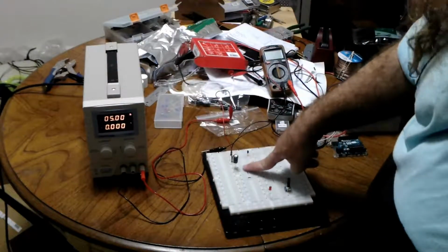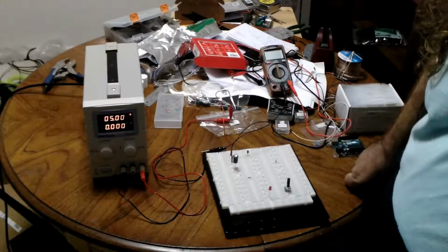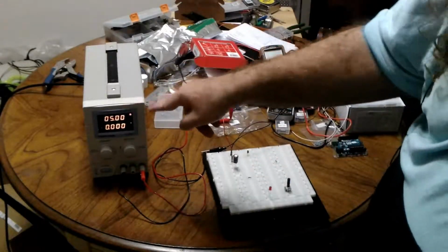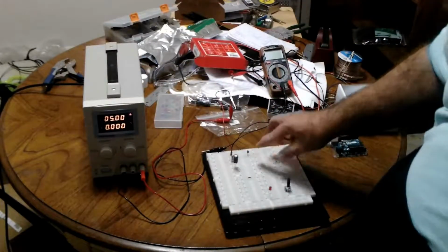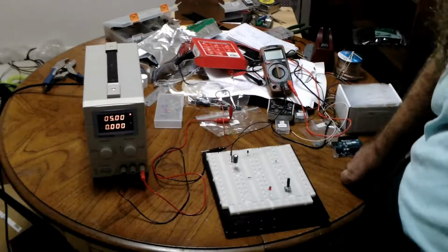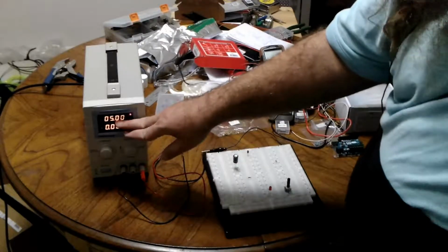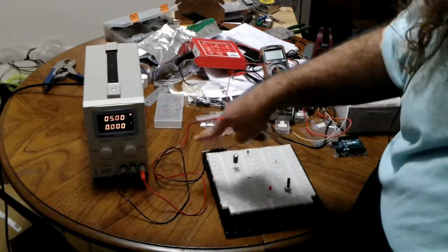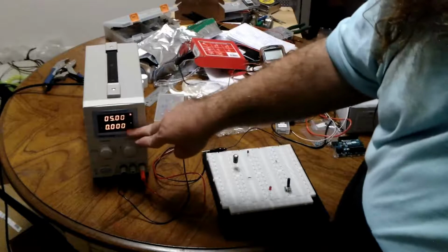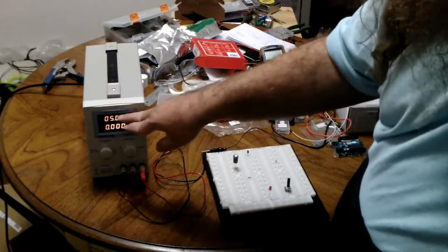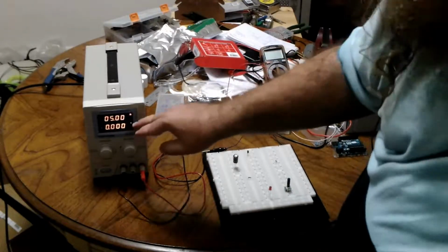So this capacitor is now charged 99.999% of the way to 5 volts. So 4.9999 volts. And if I leave it here a month, it'll probably get close enough to 5 that I can't measure the difference. But the point is, it's now charged. So it kept turning up the voltage, and the capacitor would charge to that voltage, maintaining that 1 milliamp until it reached the full, and then pretty much no current was flowing.